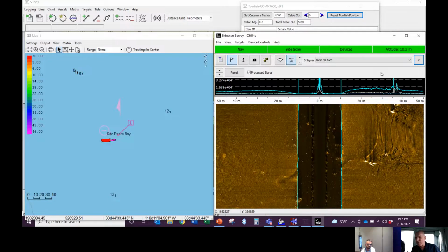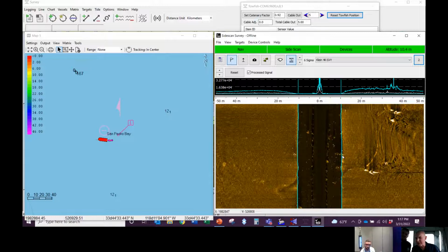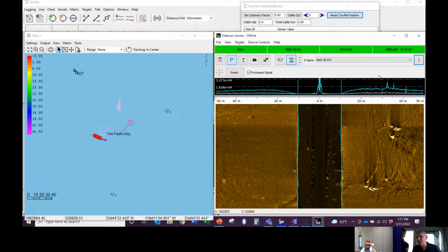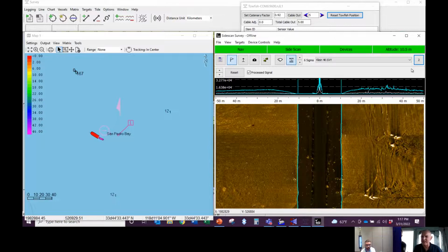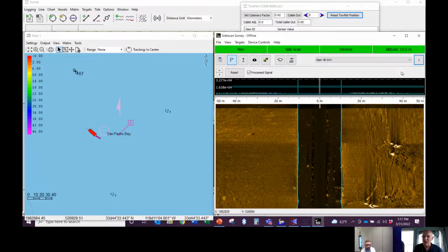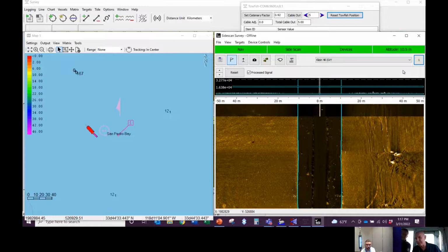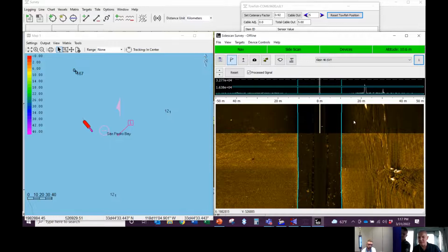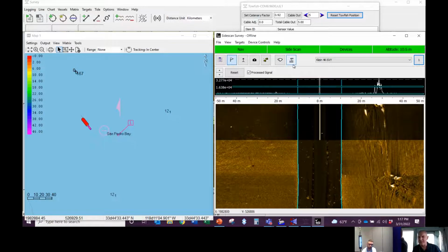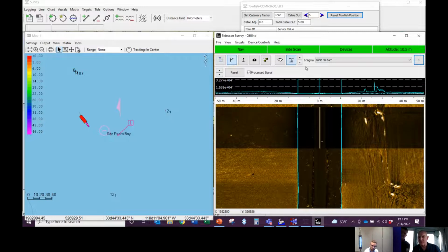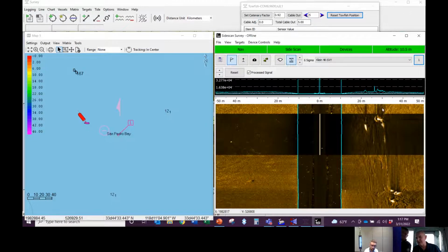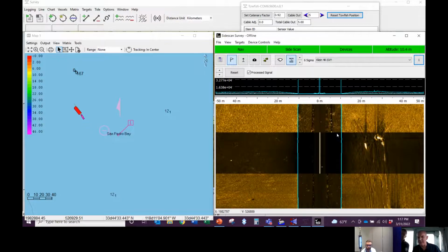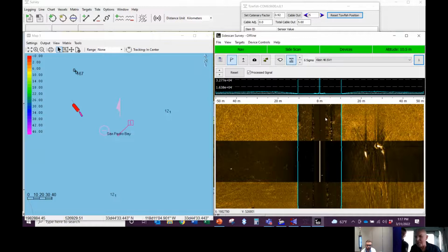In terms of the side scan waterfall data, you can see how robust the bottom tracking is here. We are looking at what HYPACK calls frequency 2, which is the 600 kilohertz. We can also look at frequency 1, which is the 300 kilohertz data as well. And this will start coming in. It'll take a little bit of time for the TVG to organize itself. Let's just put on the auto TVG, and now we can see the 300 kilohertz data. Notice again how rock solid the bottom tracking is. It ignores all this noise in the water column.